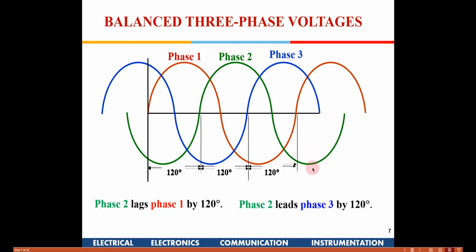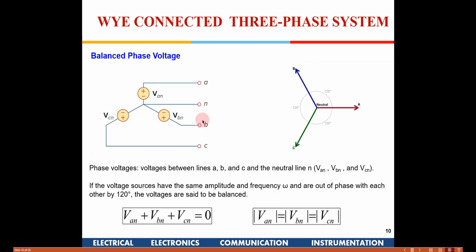Okay, so in our domestic use, all the loads are designed only for single phase and neutral. So if you are going to connect a load between two phases, then all your normal tube lights and whatever domestic appliances you have, which work in single phase, are going to burn, because you are going to apply a much higher voltage. Okay, now what is that voltage?